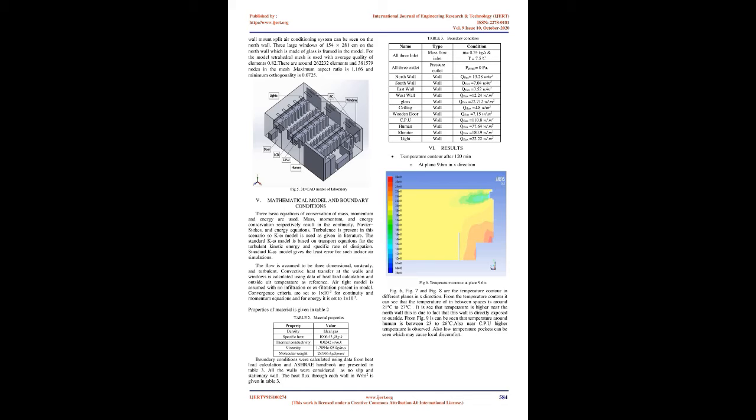B, room latent heat. Q equals latent heat gain from humans. Q equals people times latent heat released per person. Total room latent heat equals Q equals 10400 BTU/HR. C, grand total heat. Grand total heat equals total room sensible heat plus total room latent heat. Factor of safety equals 3%. Grand total heat equals A plus Q times 1.3 equals 67863 BTU/HR.